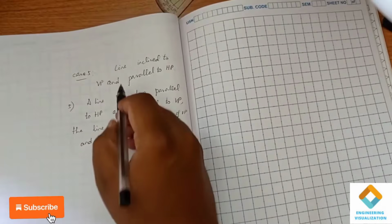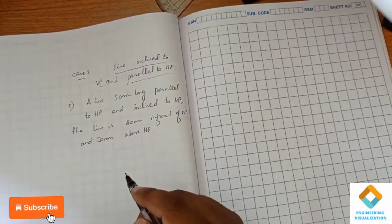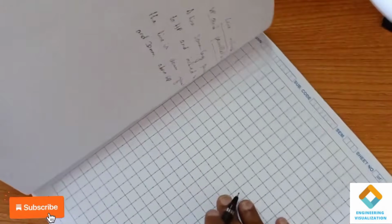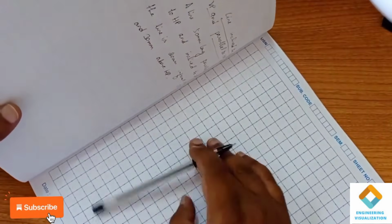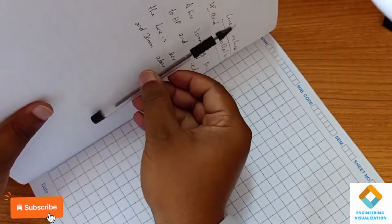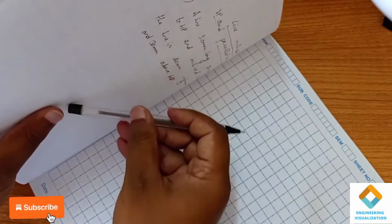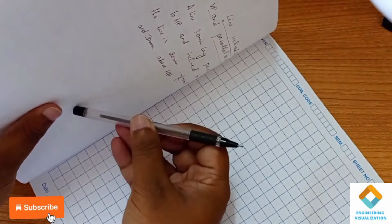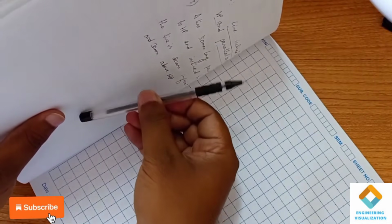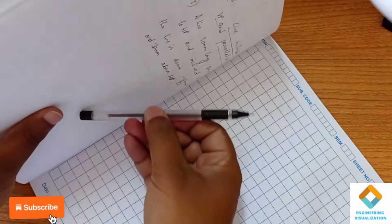The fourth case, that is line inclined to VP and parallel to HP. So how it is here, you can see this is our VP plane, this is HP plane. Here you can see this is parallel to HP and parallel to VP. Here we are giving inclination. Whatever the inclination to VP, we will give it like this, and it is parallel to HP. Okay, like this we have to do it.